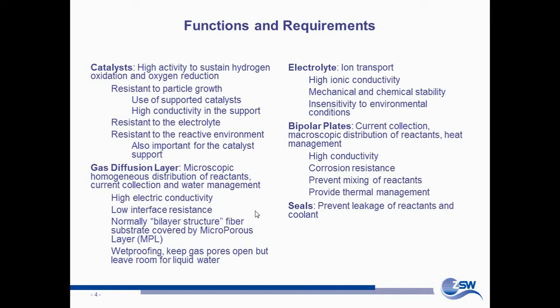Mechanically stable sounds strange, but it's a very, very thin layer, 25 microns, and it must support a lot of mechanical force, up to 10 bar. So it should be mechanically stable. It should be resistant to pinhole formation, and so on, and it should be insensitive to the environmental conditions, like having more or less water. How well that can be fulfilled, we will see.